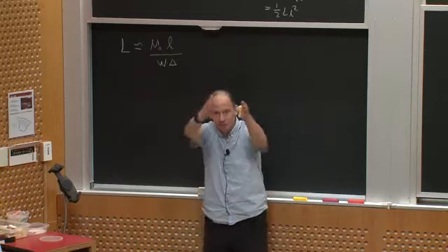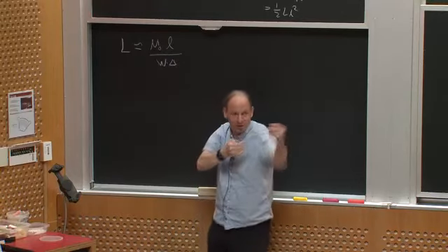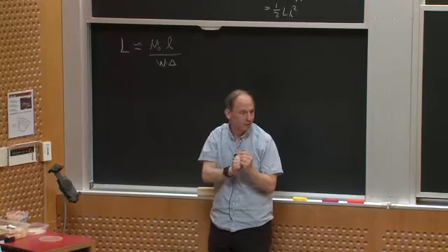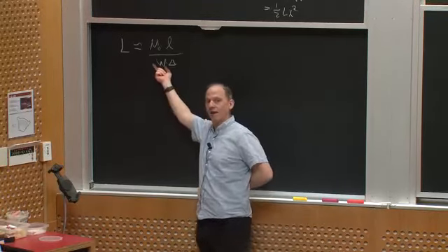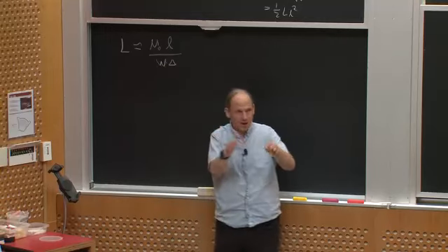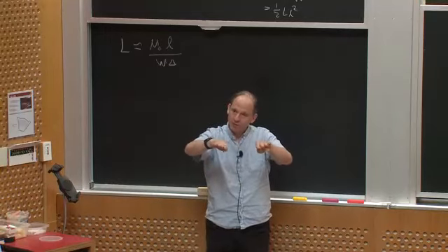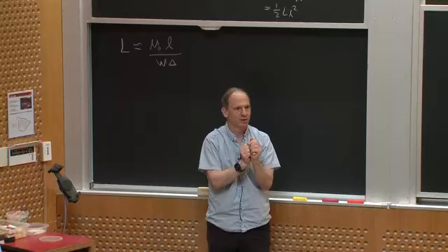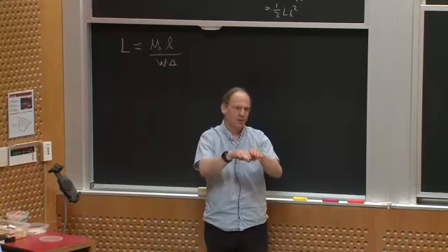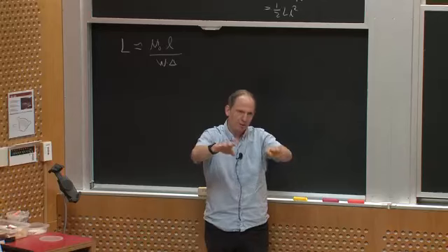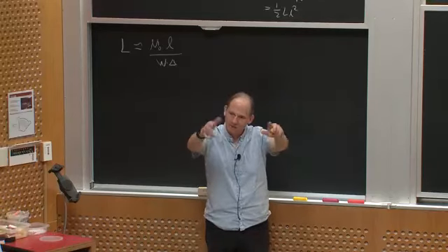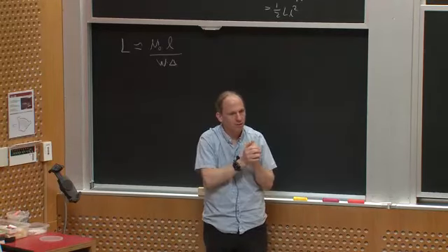Put everything as close together in terms of the length I'm carrying the current over as possible. If I have to carry a current in a trace, I would like the trace to be wide. The wider the trace, the more the current and field spreads out and the lower net energy stored. Okay? Because the width helps me reduce the field magnitude, and even though I'm carrying it over a wider space, I have more volume, I get a lower inductance.